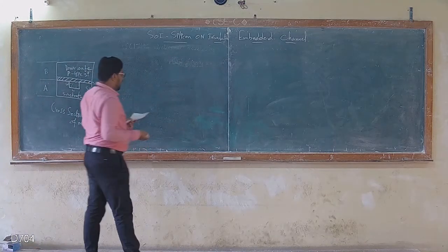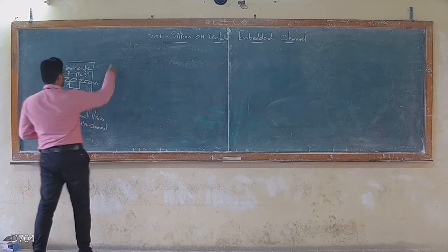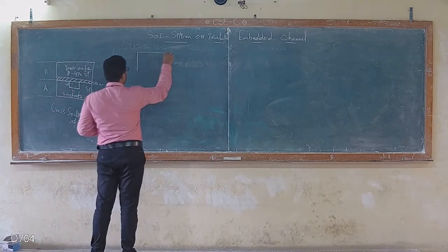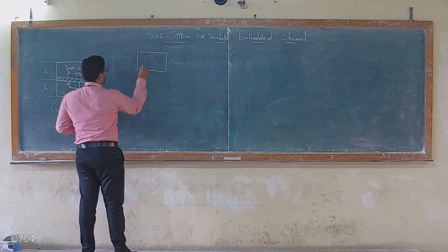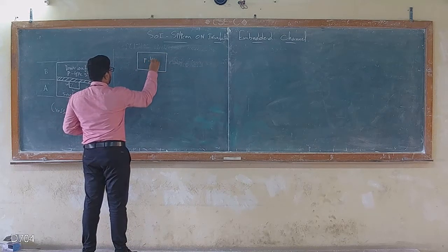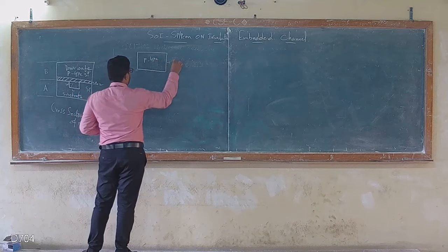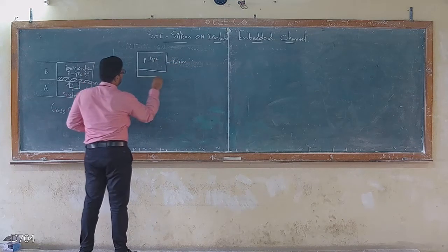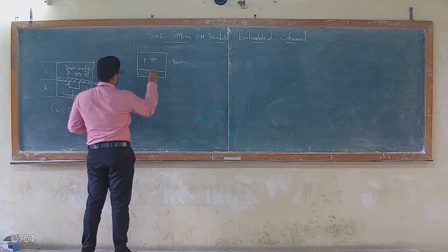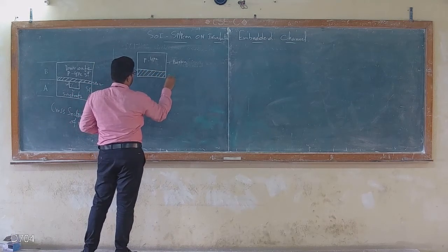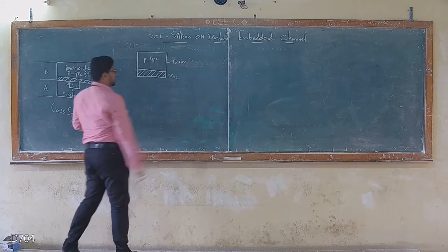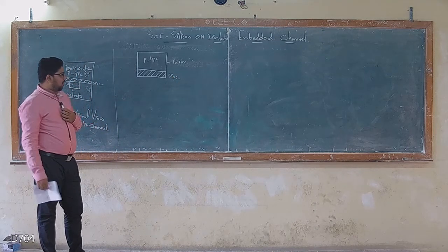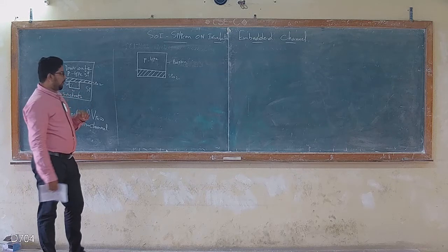Let's start from the process. Initially it has a donor wafer. It is made up of a P-type semiconductor with boron implanted. Along with that, we have a SiO2 layer, which is developed by an oxidation process, either wet oxidation or dry oxidation. Anyway, it's a simple process.